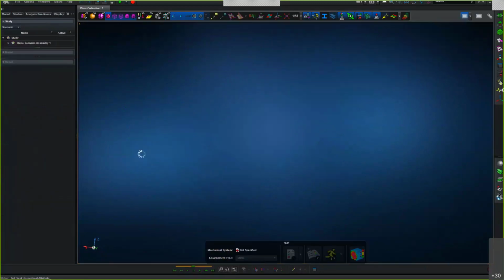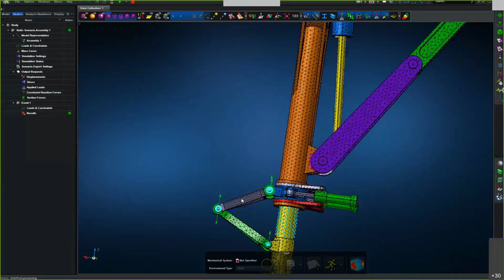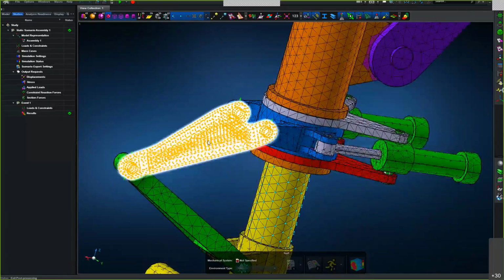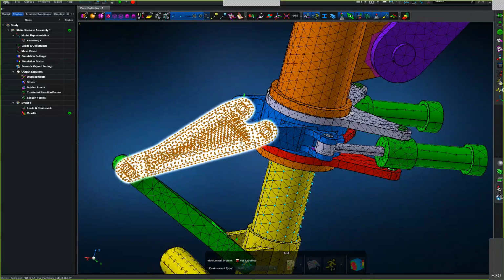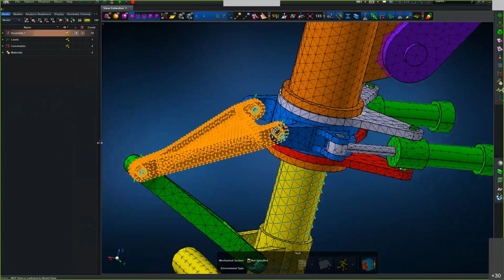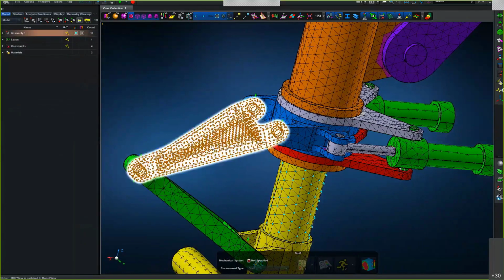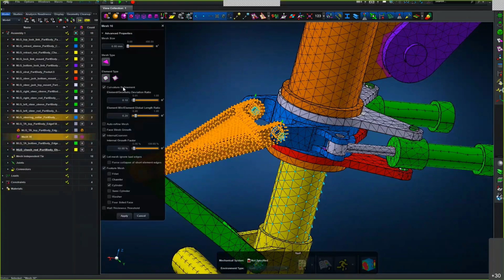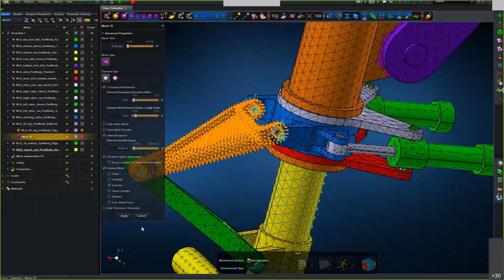shape. So if I go back out and I say, okay, well, let's say I got a new design for this part here. So from this part here, I can find where this part is, and take a look at the mesh here. So I can see I've got a 6mm mesh. It's got linear elements, etc., curvature refinement, a whole bunch of options.